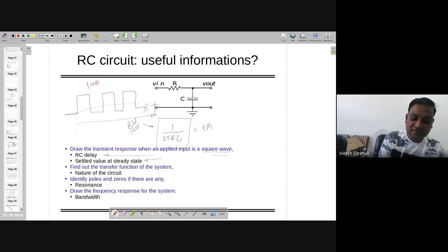It takes so much time to reach here, but before that the output has to change because input is changed. So your output will look something like this, right? And if you increase the timing, you will understand that the things are as good as you are seeing something 0, and that will be treated as logic 0 depending on your noise margin, high or low. So that's what we need to understand, that we have to restrict ourselves to the given time constant.